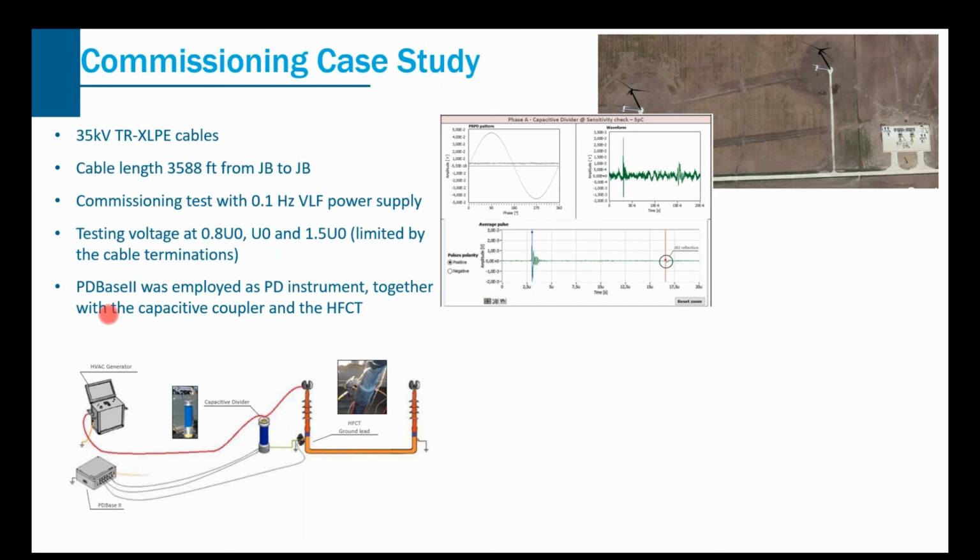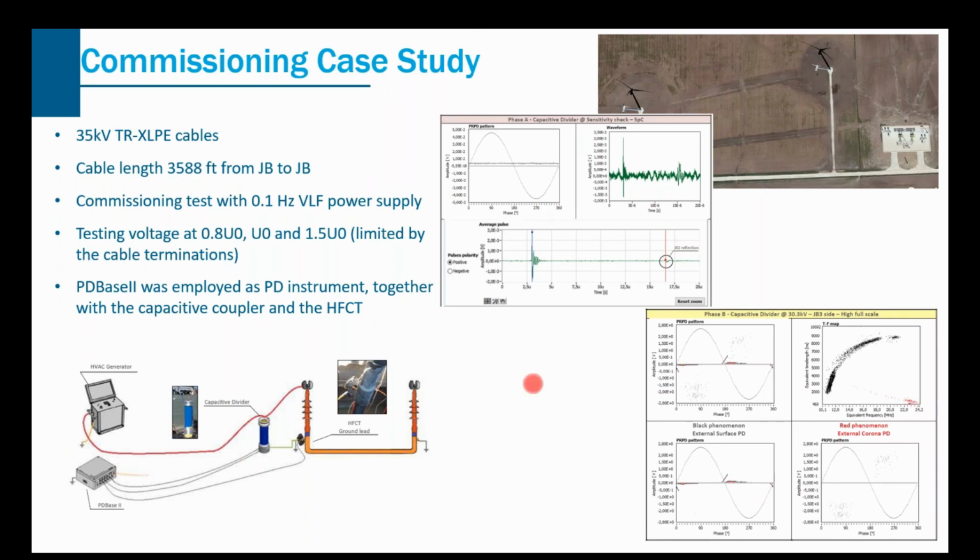And here is the acquired discharge pattern. There are some activities, and we use the TF map to separate the signals from different sources. And the 2 types of discharge activities or clusters can be distinguished and separated. And we do the analysis on each individual cluster, and that requires the criteria that we talked about in the PD detection technology. We need to locate where the sources are, and we need to evaluate if those PD activities are harmful to our system or not.